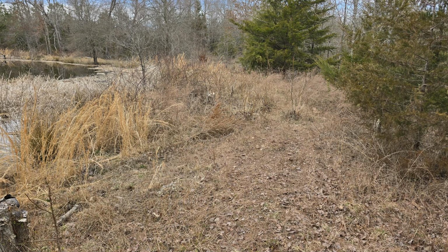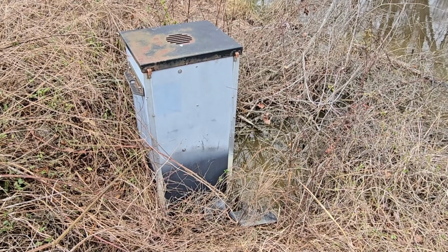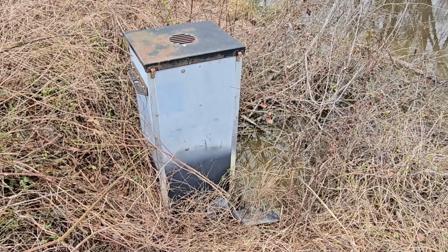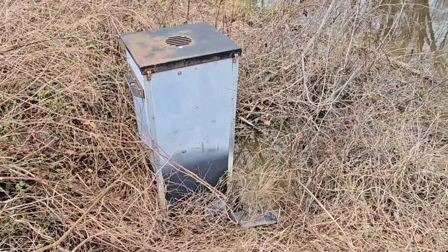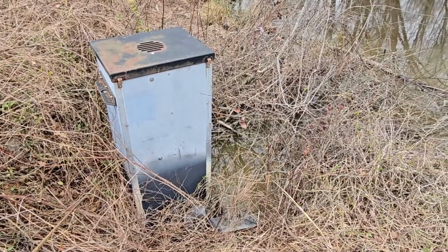The dam for this wetland is not holding water. The main reasons are that the water control structure was left open and there are muskrat holes that go through the dam. Here's the water control structure that was left open. This is called an inline water control structure that's made by AgriDrain Corporation.